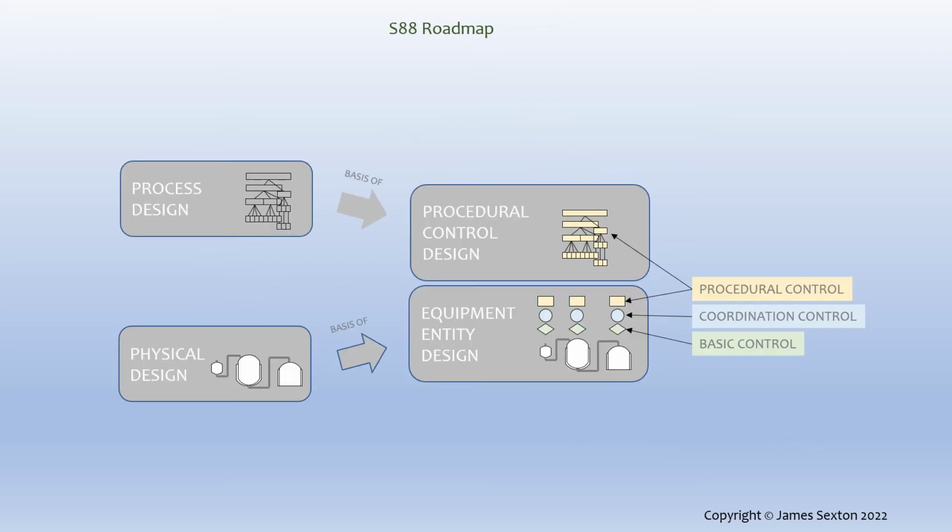By categorizing the three types of control in an equipment entity, the ISA-88 framework is guiding designers to ensure that all control requirements are captured in a systematic way. It helps us name every physical and logical resource, and that results in a complete and unambiguous description of the piece of plant that is being modeled.